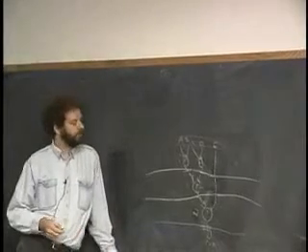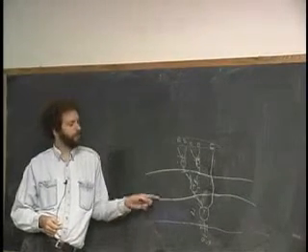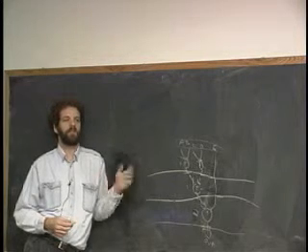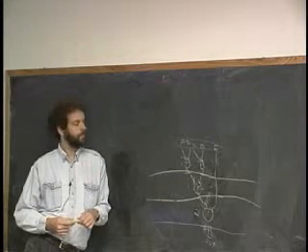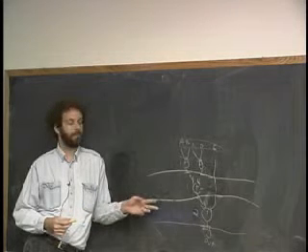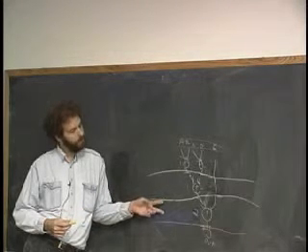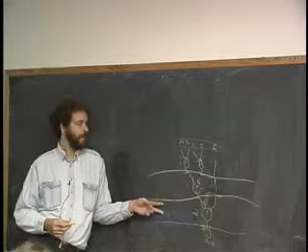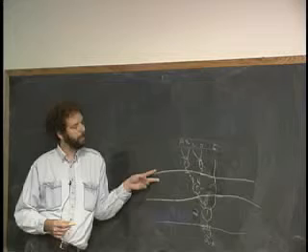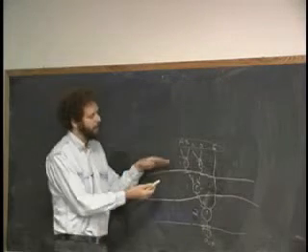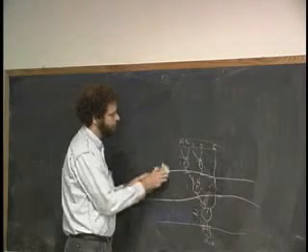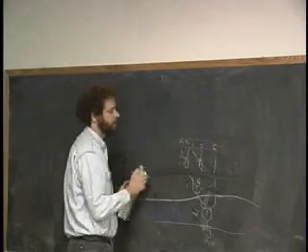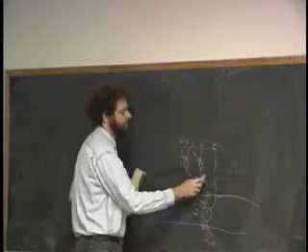Let me ask a question. Is it necessary to actually have 3 stages here? Or am I sort of wasting pipeline registers? I only need 2, really, right? So I want to surround the element that's the bottleneck, that's the slowest one, with pipeline registers. And then over here, I can go around the circuit and say, I can accumulate up to 2 units of delay here and not use a pipeline register, and I'll still get the same performance out of the system.